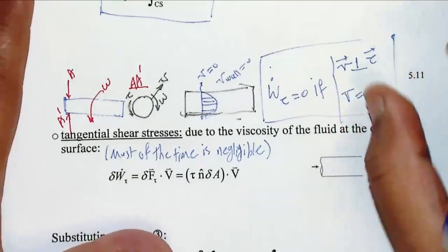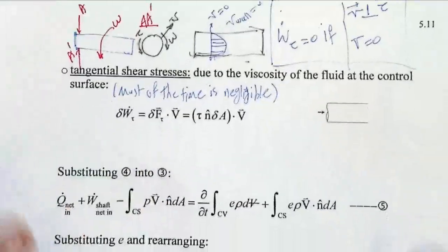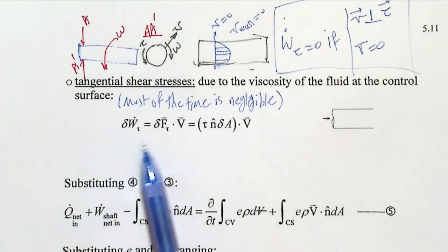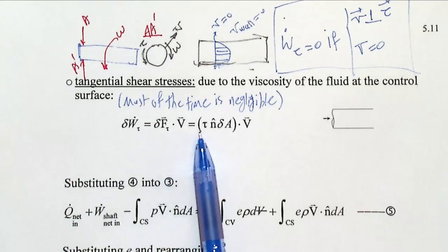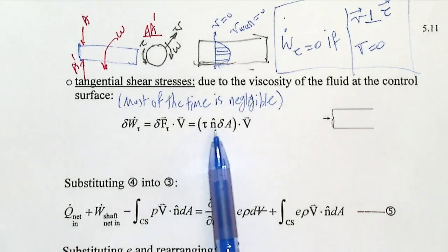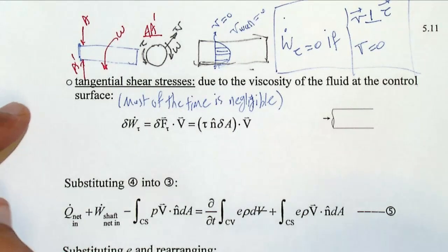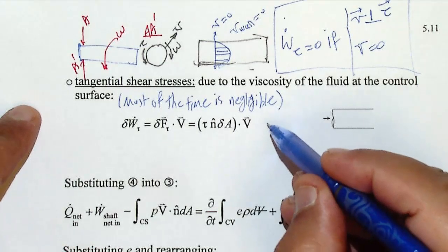But in terms of equation, if you by chance had it, the same definition applies for W dot of tau: force times velocity, and the force is going to be tau times area, times n, and you can bring the V dot here, and you can write the same, that is going to be V dot n.